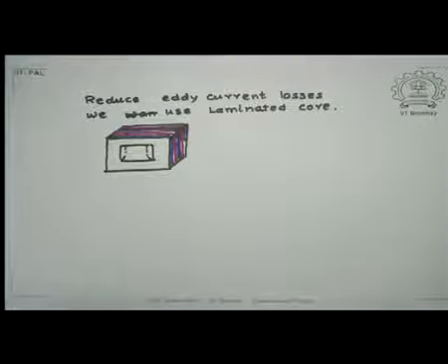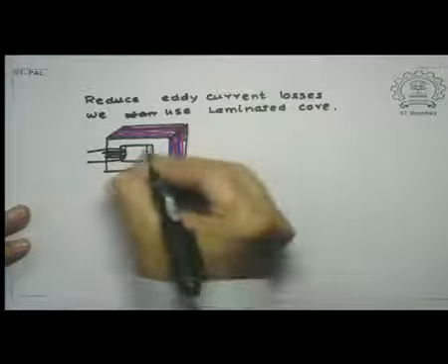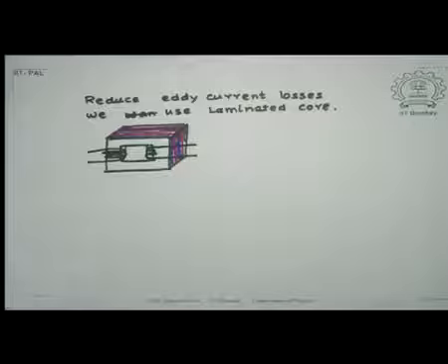And of course, likewise, I have this section, and here my windings are there. So these layers or laminates are glued to each other by thin insulating coatings, and this helps reduce the eddy current because the thickness of each individual layer being smaller, the available area for these currents becomes smaller, and as a result it reduces the eddy loss.